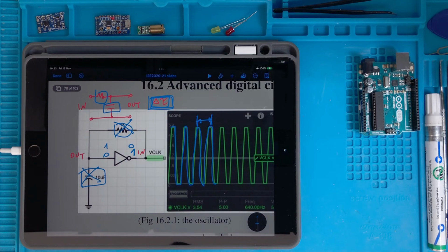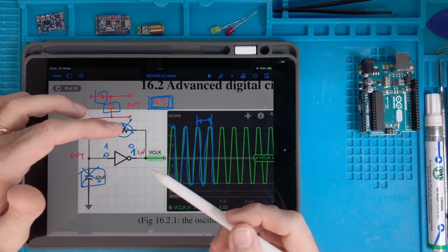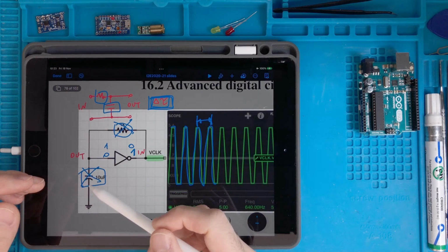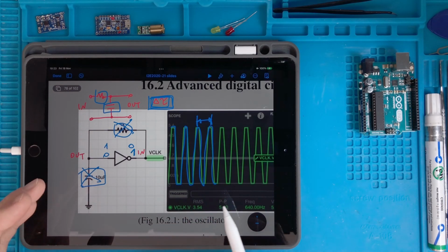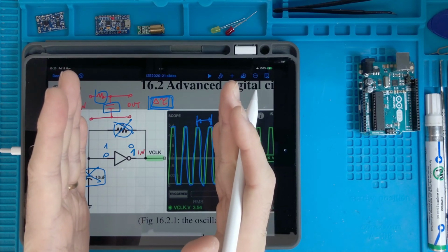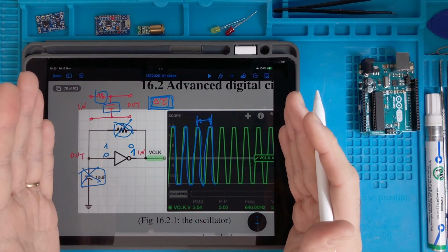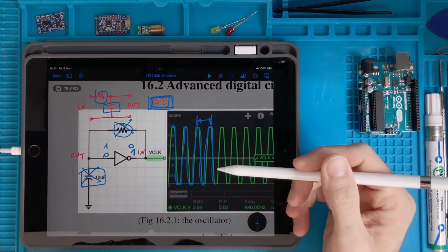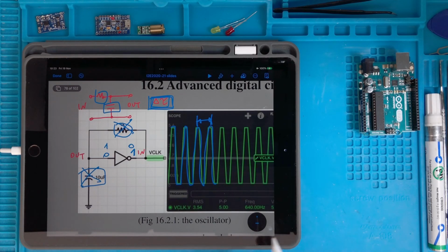You can't really produce a resistor with an infinite amount of resistance, which means that you can't really disconnect this resistor, and you can't really produce a capacitor with zero capacitance, because the capacitance is the result of two pieces of metal close to each other, and even if you put them far from each other, they still exist. So they have maybe a little capacitance and a high resistance here. It might be that these oscillations are very, very rapid, but they are present.